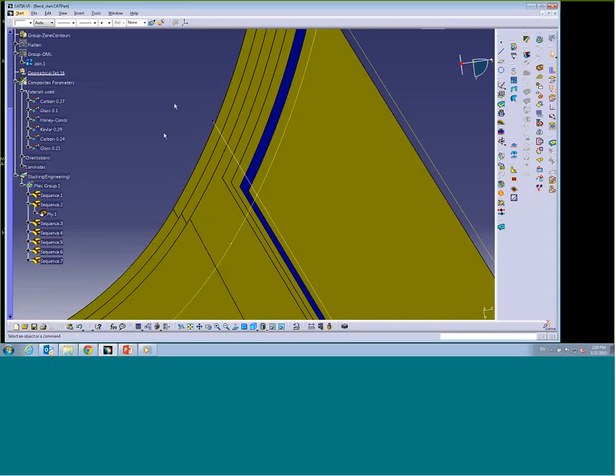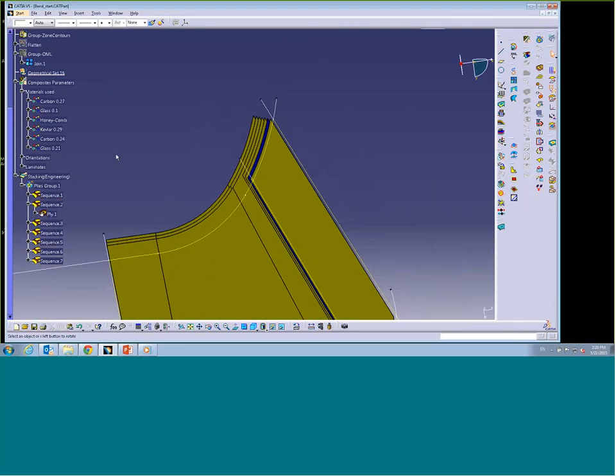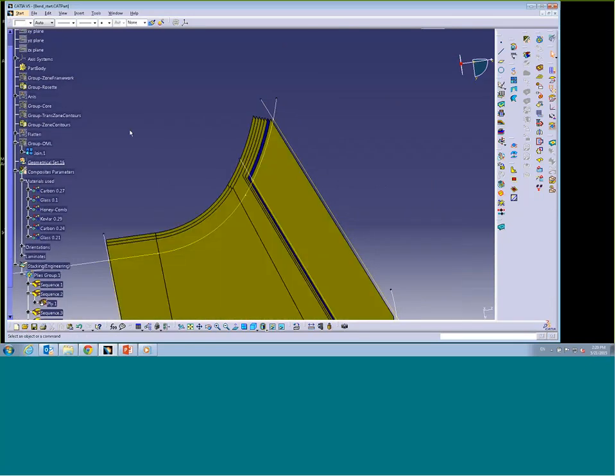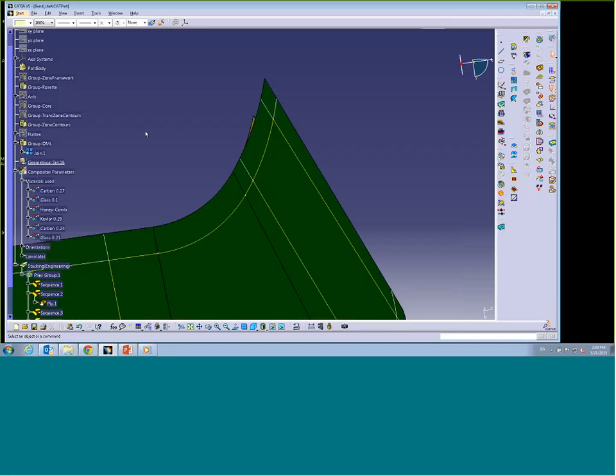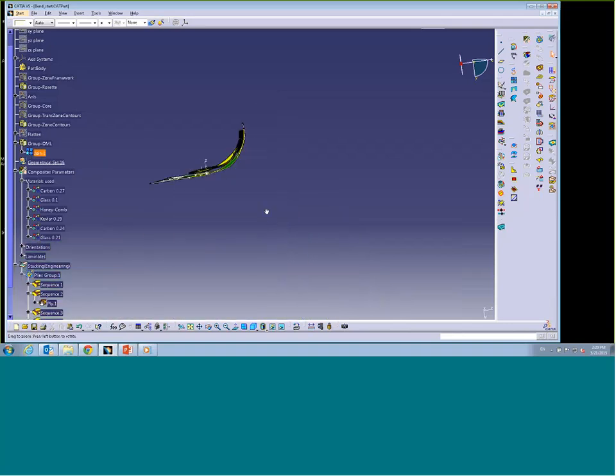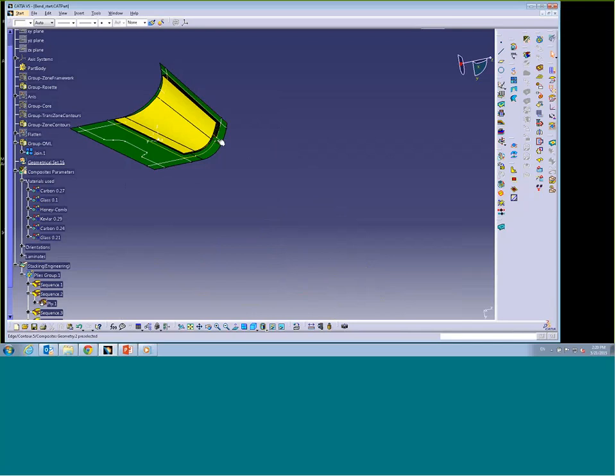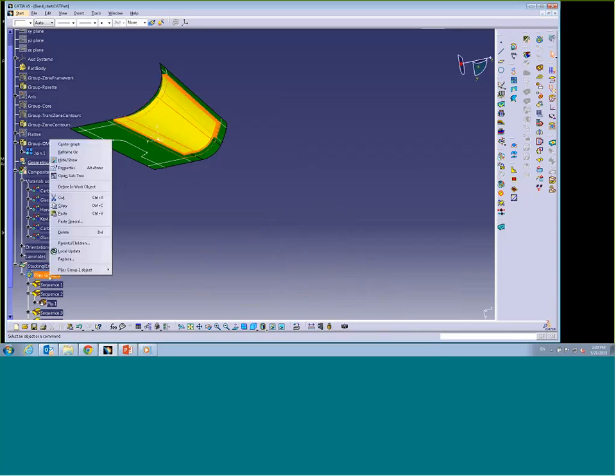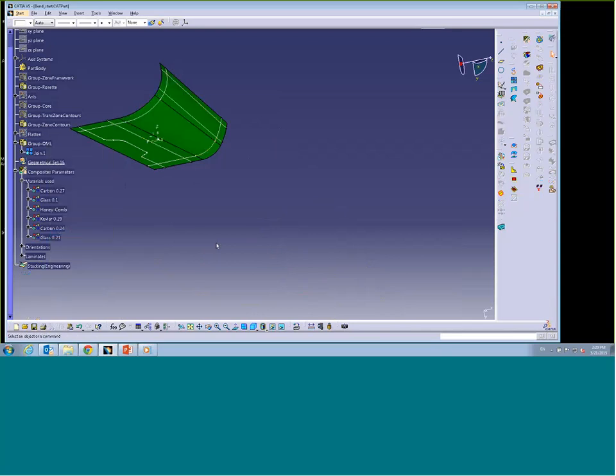Could I do it using manual plies? Yes, certainly. What's the problem? I would need to create a lot more of those curves. So basically, for every ply, shorter plies, I would need to create a curve on the surface. Very tedious work, but there is a better way. So now we're going to be using zones. So I'm going to get rid of this one, manual plies, and I'm going to start with zones.